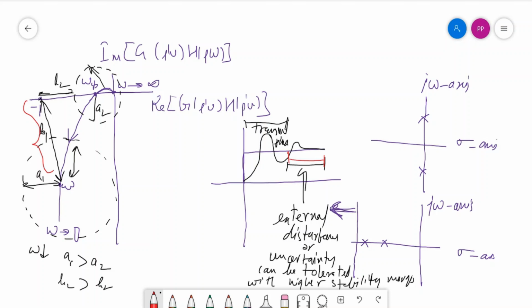At the same time, I say that if there are poles on the imaginary axis when the system is reaching the low frequency region, at that time the presence of complex roots of the poles will cause the system to be more vulnerable to instability, because this is the situation I am telling about.